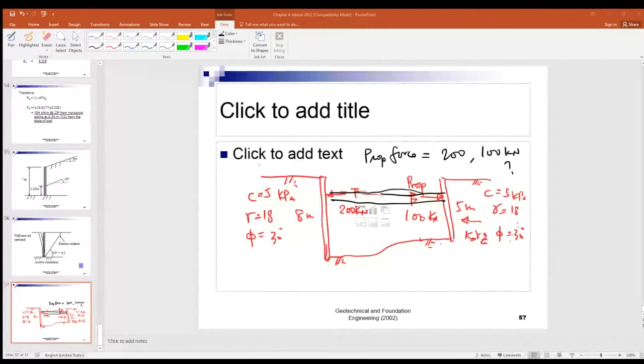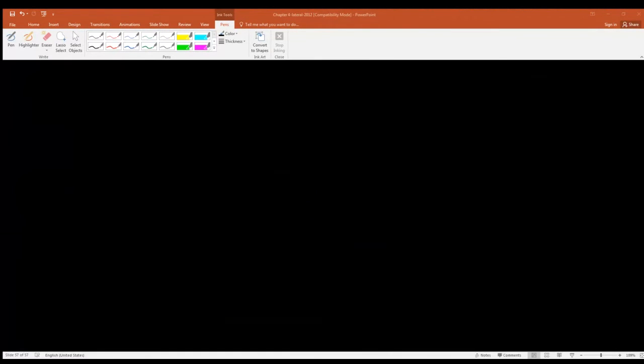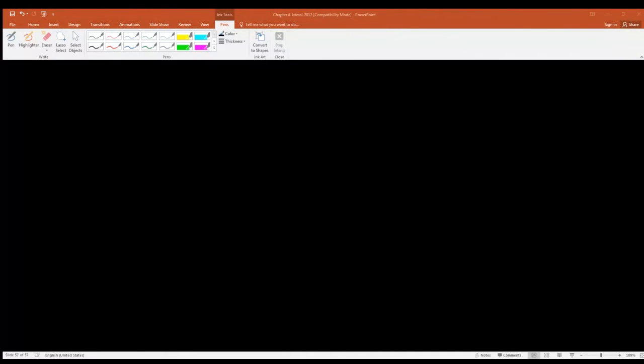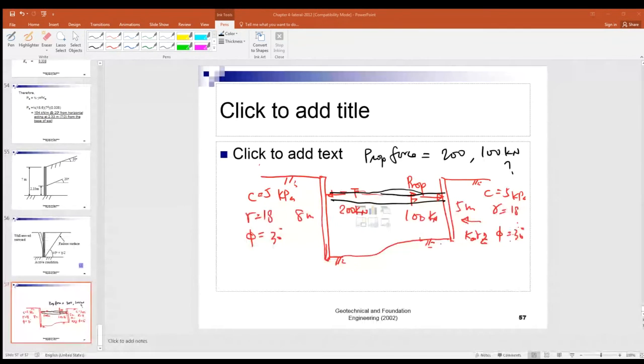Why do we need a berm there? Why do we have to do a berm there? Simply for the maintenance, right, of the slope. So you have a surface channel there, so the guy could come up, right, and then do the cleaning of the surface channels.